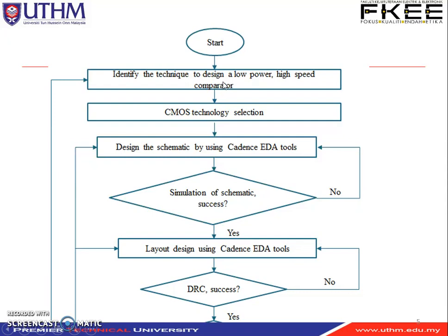To have low power, we must use a low power supply. So in this design, we are using a 1.2 volt supply. For the CMOS technology selection, we are using 130 nanometer CMOS technology, and we design the circuit using Cadence EDA tools.